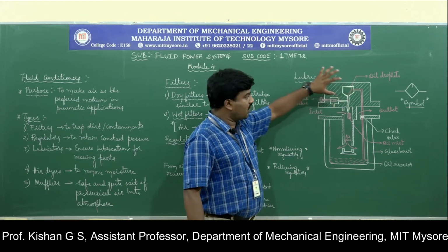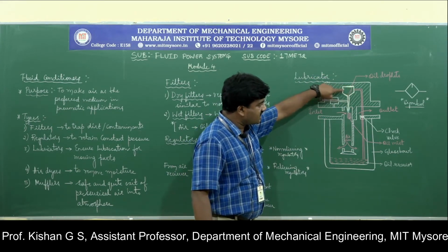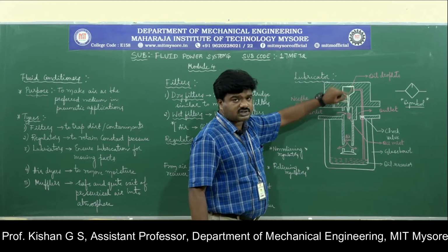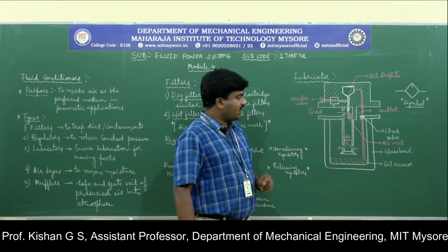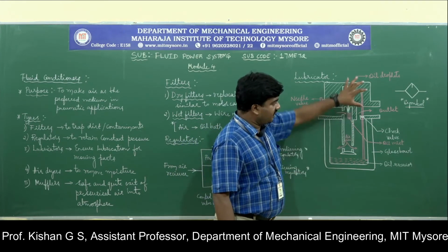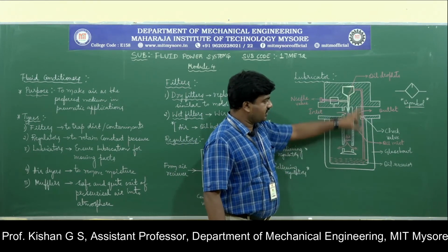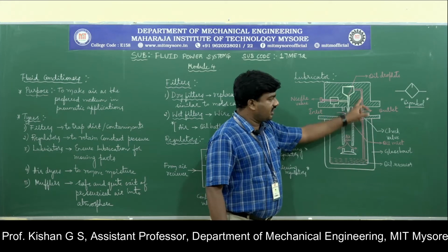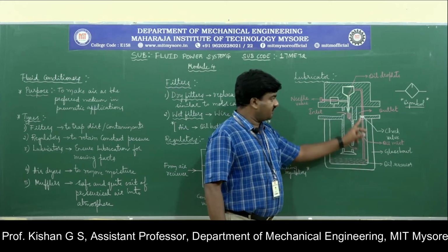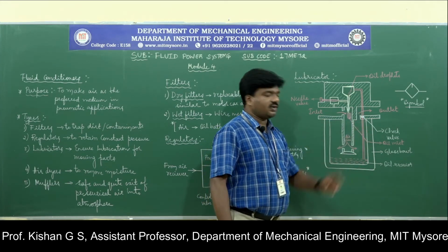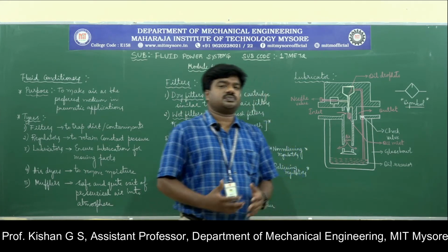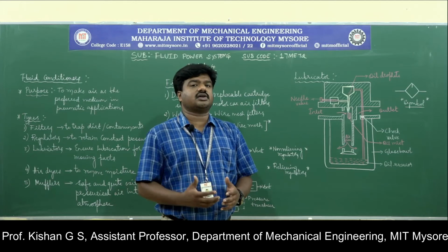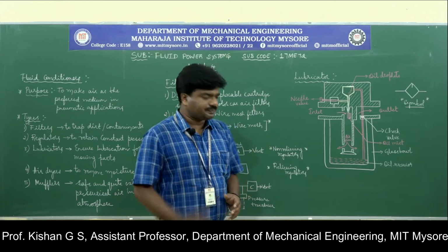If you observe, there is a space for the oil droplets, there is the presence of a needle valve, and the connectivity between the upper portion and the lower portion is held through a capillary tube which is fitted with a check valve here. The basic functionality of all these components plays a vital role in understanding the concept of the lubricator.